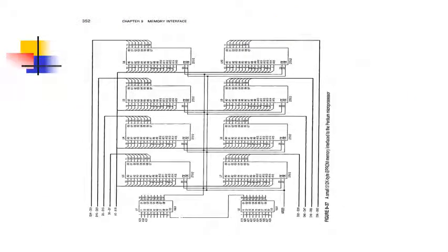Here is the wiring of connecting or interfacing the Pentium 4 with 8 different banks. These are the two PLDs, programmable logic devices, which are used to select a low signal that goes to the chip select of each of these 8 banks. Here is the address A3 through A18. This address goes to each and every bank. Okay, good. And this is your data bus.